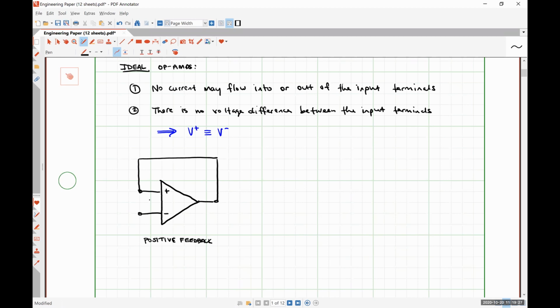So you speak, it generates a pressure wave, which is picked up by the microphone and then amplified by the speaker cabinet. Well, the speaker cabinet also produces a pressure wave, which can be heard by the microphone. And so you get a cyclical increase in the output signal that results in that high-pitched squeal that most of us are not very fond of hearing, okay? So that would be representative of an unstable system, which is what most positive feedback systems are.